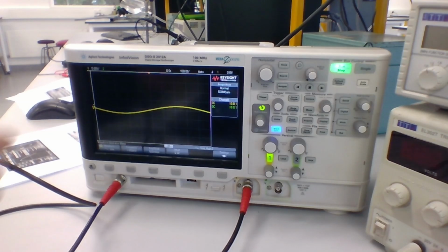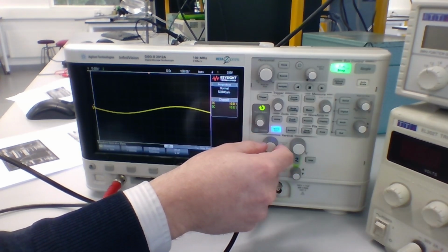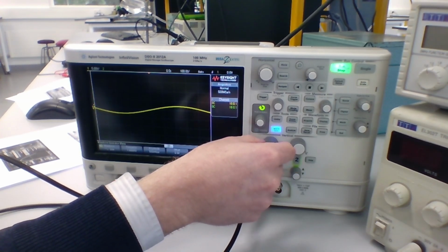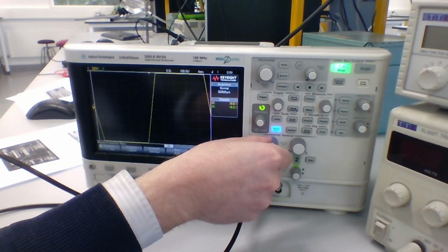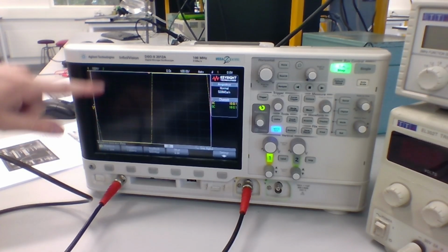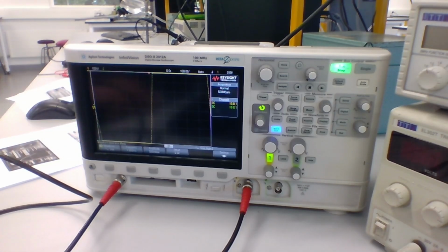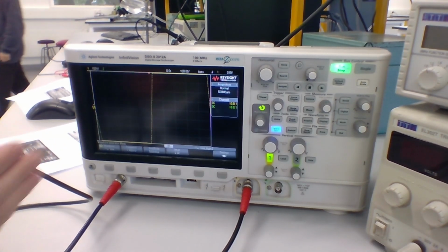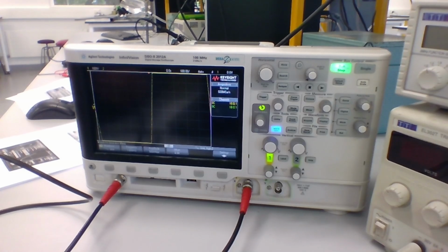I'm also going to set the oscilloscope scale up as instructed, which is 100 millivolts per division and 100 microseconds per division. I've set this up as instructed, but we can see that the waveform has gone way off the screen. We know this is a 500 millivolt peak-to-peak sine wave, so at 100 millivolts per division vertical scaling, this should fit on the screen quite nicely, but it's not. The reason for that is that we need to set the attenuation factor of the oscilloscope correctly.